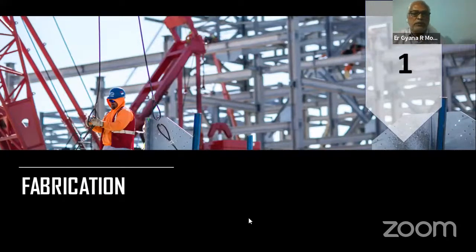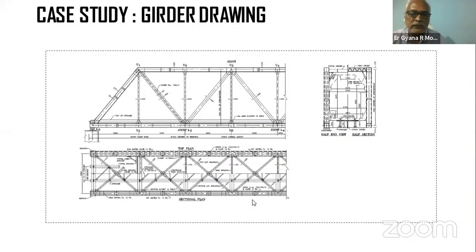So today our topic is fabrication. As a case study, we'll take a 45.7 meter span, and there are several components. There are I-beams, there are built-up sections. All these sections have typical welding parameters, welding sequence, and welding procedures. That is why this particular span will give us an insight into the precautions and the ways we should fabricate any steel girder. You'll almost have everything.